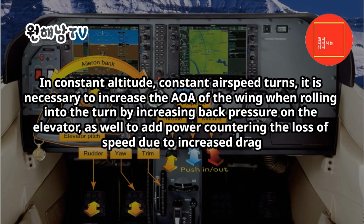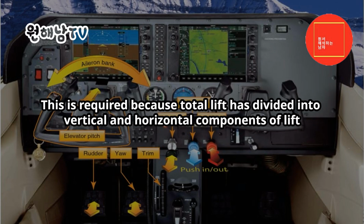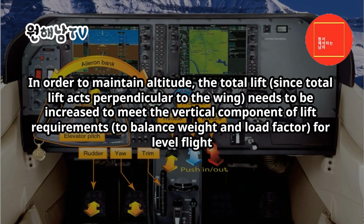In constant altitude, constant airspeed turns, it is necessary to increase the AOA of the wing when rolling into the turn, by increasing back pressure on the elevator, as well as to add power, countering the loss of speed due to increased drag. This is required because total lift has divided into vertical and horizontal components of lift. In order to maintain altitude, the total lift, since total lift acts perpendicular to the wing, needs to be increased to meet the vertical component of lift requirements, to balance weight and load factor for level flight.